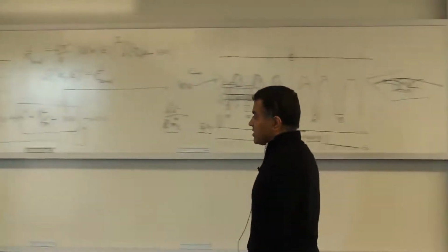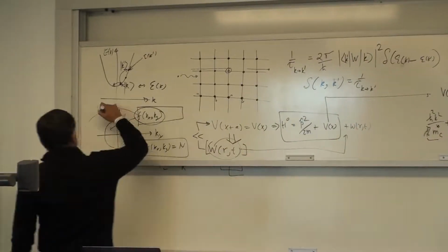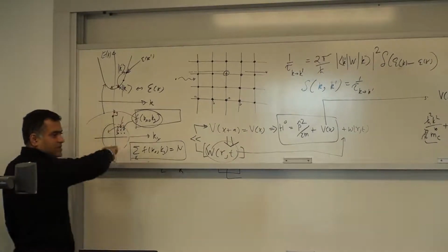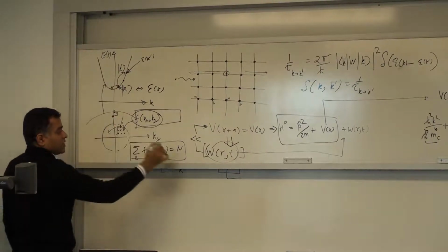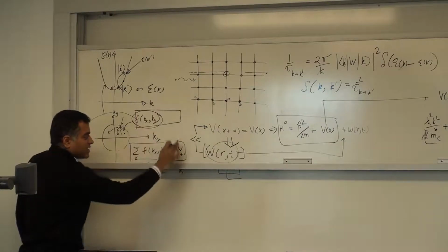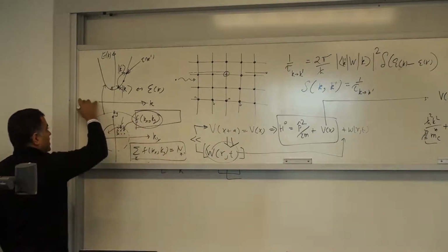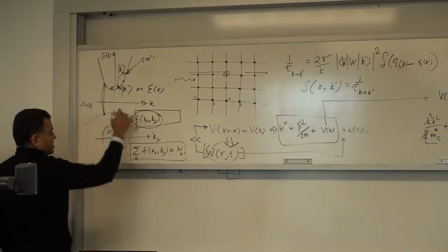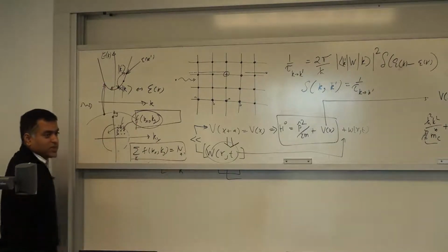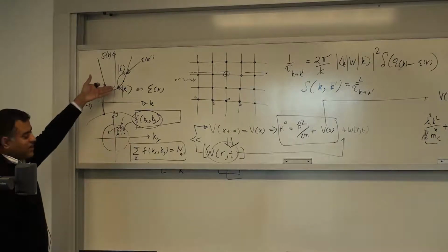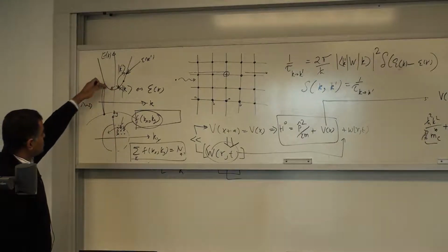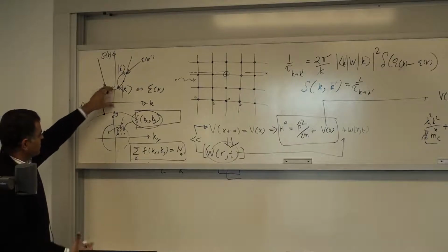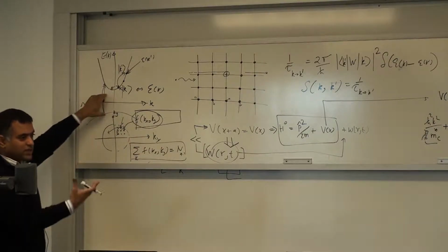That may happen, for example, when you have interband tunneling. An electron can tunnel from here to there. That's interband tunneling, in which case you just added one more electron to the conduction band, right? Or you can have light come in and this electron absorbs that photon and goes up, in which case you also add it. Those terms are called generation terms. And if you similarly lose electrons from here, maybe there are some holes here and the electrons were reduced, that is called a recombination.